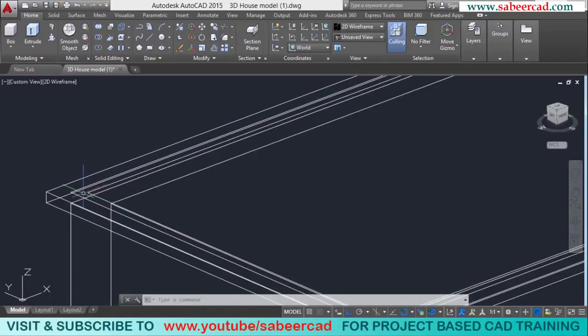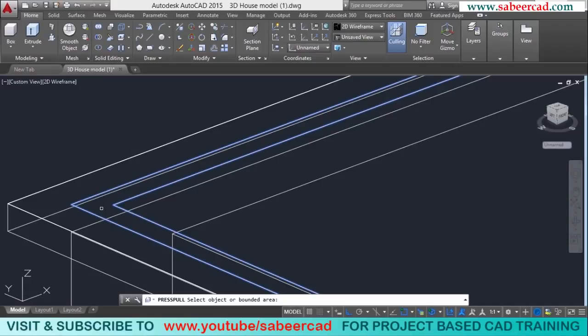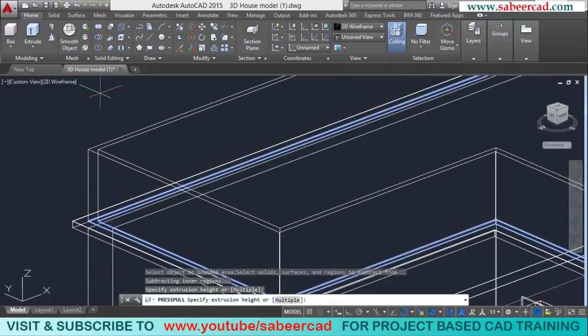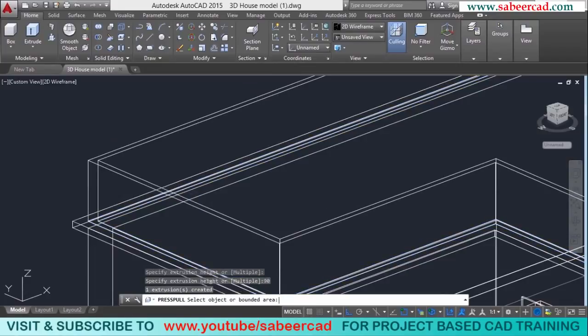Next, I'll create the parapet wall by press pulling these two profiles. So I'll just click on the press pull command, or else you can type press pull using the keyboard, and I'll just give a click at the middle of these two profiles. And you can just take the cursor in the upward direction, then you can type the value, which is 90 centimeter. So I typed 90 because that is the height of the parapet wall.